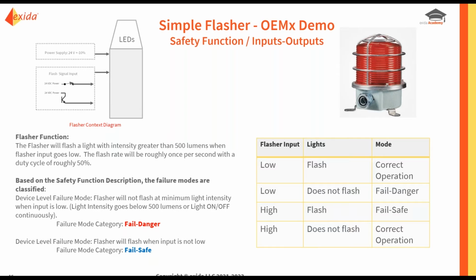I can see that the device is used with an external power supply of 24 volts, and there is a signal. It sources current, and the input goes high when the current is sourced, and the input goes low when the current isn't sourced. Okay, I can see what kind of input it is and how it works by knowing it's a current source digital signal.